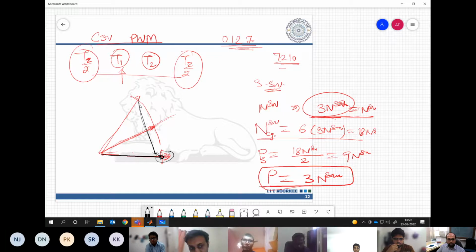Yeah, 1 degree. But what about this voltage error? This voltage error will be applied for a very small time, and as the difference between the two is very small, the net ripple current will be very small, na, sir? That is there, but what is the quantification of that very small? I just started quantifying it, but roughly it was coming out as a smaller value.